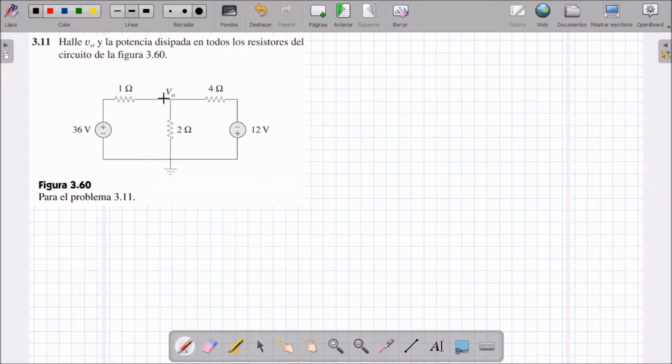What I always do is a visual analysis of where the currents can circulate, and then I add the names. I see that this voltage source is 36 volts, with the polarity more or less, so the current comes through here until it reaches this point. Where it reaches this point, it has to take a path to other sides. The first one that comes to mind is for this one, since it is pointing to ground, and the second is going to be for the resistance of 4.